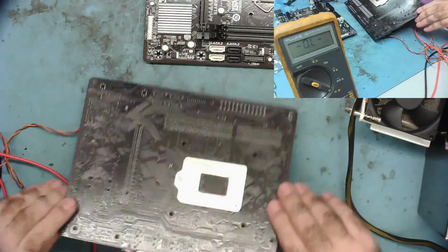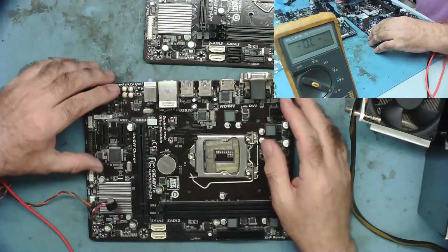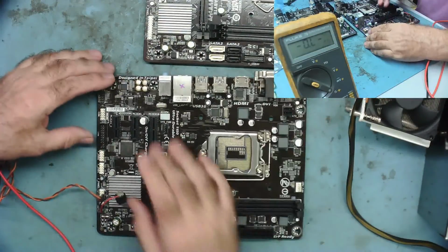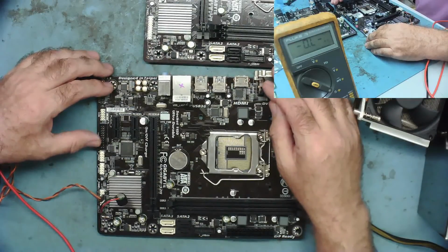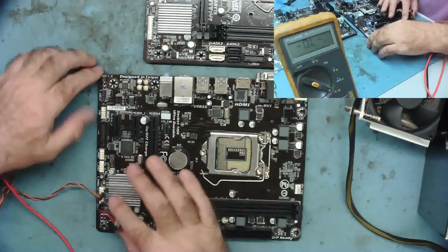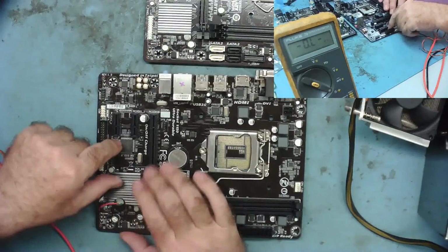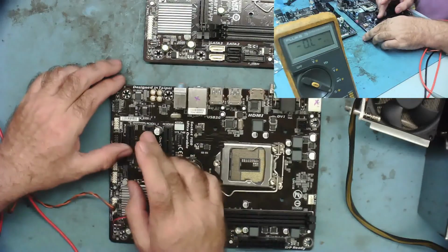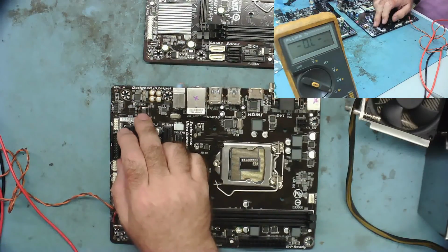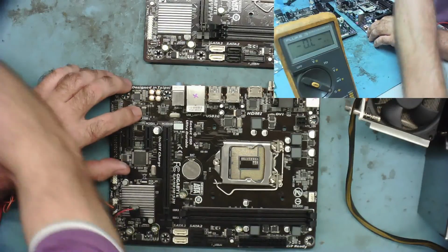So there's no resistance problems. I don't think we've got a situation where something's drawing current and shutting down. It's the logic telling us to shut down. Which is probably going to involve the PCH and the SIO. These two chips are going to be involved. I think the first thing we'll do now with this one is reprogram the BIOS, just to eliminate the possibility that we have a corrupted BIOS doing this.